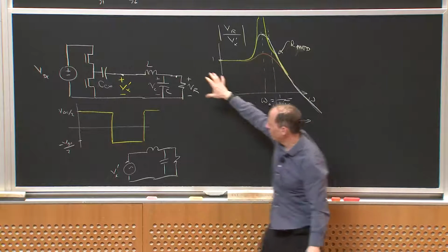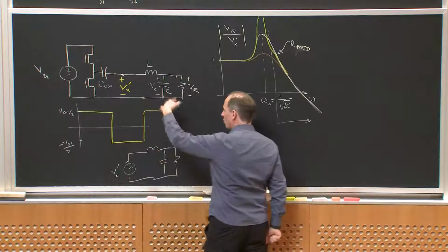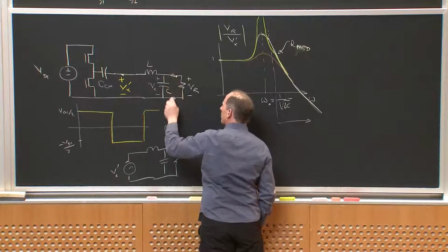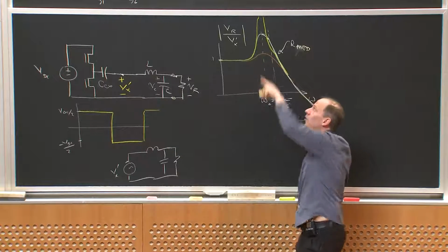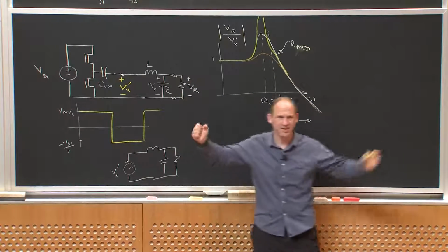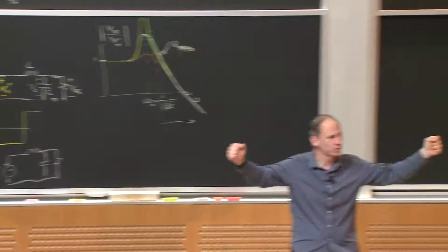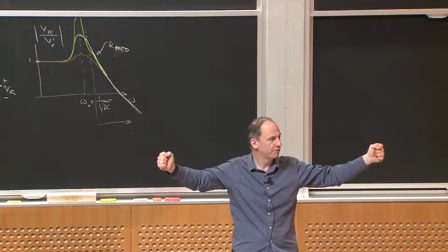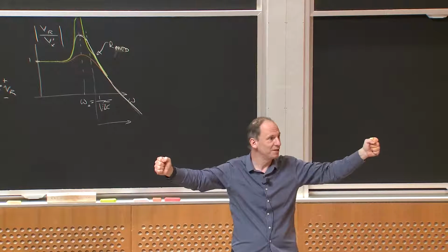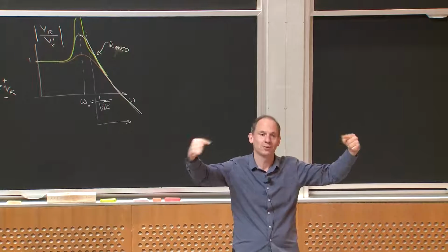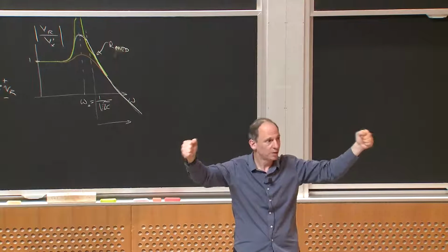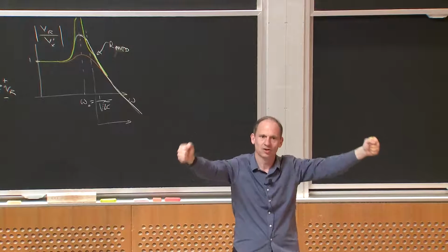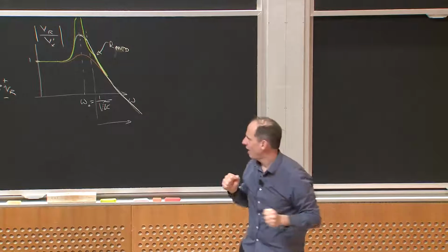This kind of network is often what's used if you're going to have a fluorescent bulb. If you think about one of these fluorescent bulbs, what is it? It's a tube with low pressure gas in it. If the lamp is off, that has a really high impedance, because it's just 2 electrodes with some gas in between. And you've got to get a really, really big voltage on it to break down the gas and so-called strike the lamp. Well, how can I do it?